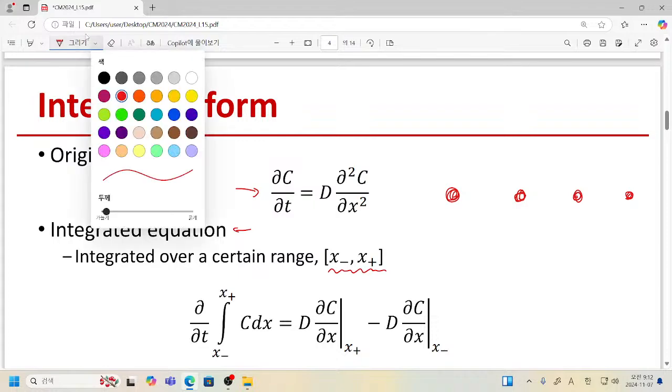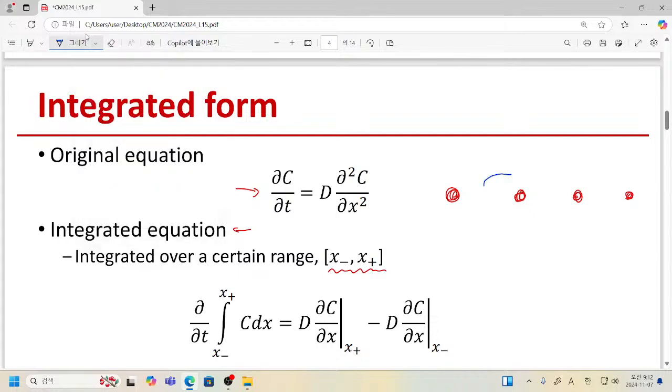Please note that in our uniformly spaced grid points, please make a comparison for the control volume. If I use a blue color to represent the control volume of each point, how does it look like? In this case, maybe this blue range will be assigned to this second dot. And please think about this third one. Yes, you may feel that this is the right control area. Then obviously the next question is, how about the situation in the very first node?